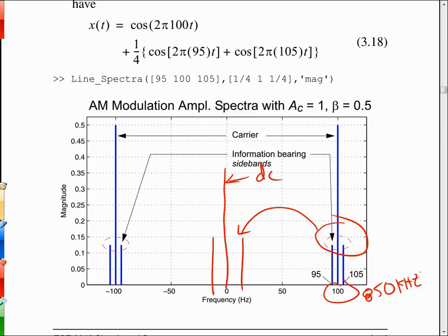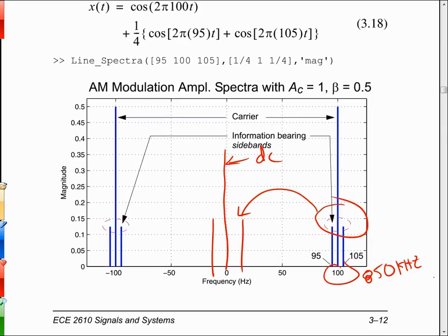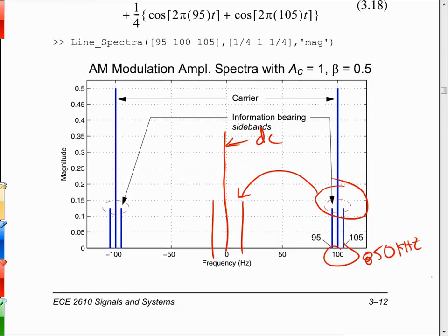And as a person that does fly occasionally, you wouldn't want to know that somebody's whacked out wiring in their house was causing some radiation out of their house, and an airplane flies over and gets jammed and can't talk to the tower or something. That'd not be too cool, I don't think, right? The spectrum helps tell us what's going on, though. So they would have a receiver that would basically be a spectrum analyzer, and they'd be able to see where that leakage is occurring, and then they can turn that antenna and directionalize and find out which house it's coming from and go in and deal with it.